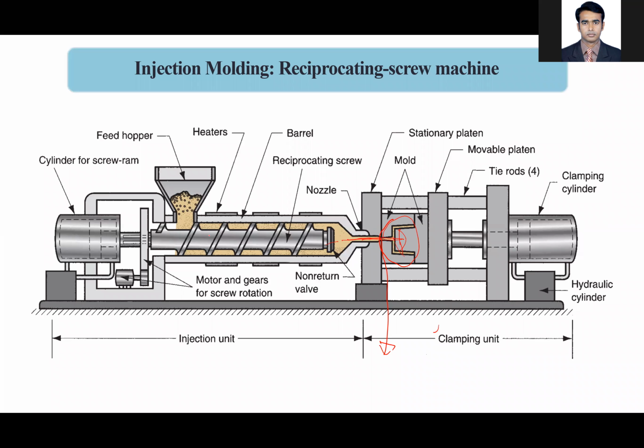And the function of the screw is only to transport the polymer material, and to take the material out, the ram comes into play. It's a discrete process. In that case the screw depth was gradually decreasing, and in this case also the screw is gradually changing. Actually, this figure does not show the thickness. But in this case also, you need to use that, because if you don't do that, there will be a lot of pores because of the initial material.